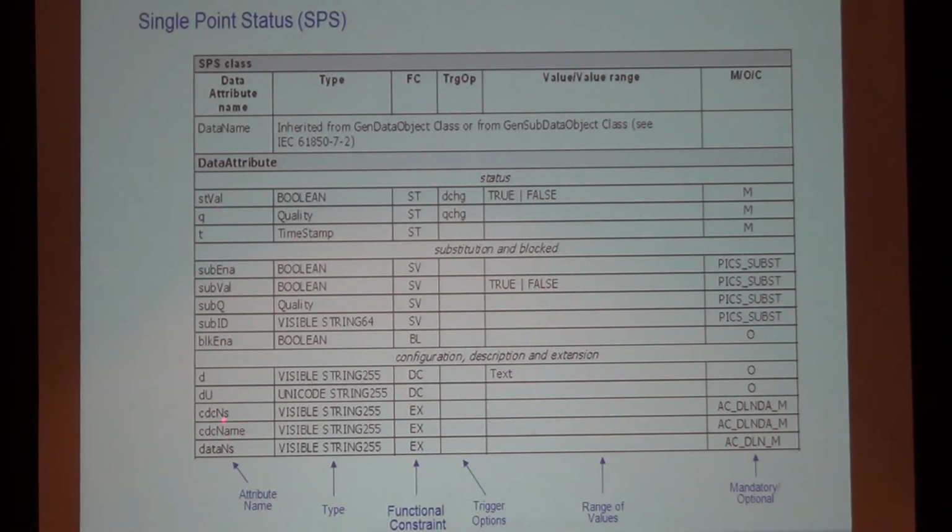And we also have these very interesting attributes that tell us about the namespace of the object. They are optional, but these are important attributes, because if the supplier or the developer of that object has provided some proprietary extensions to it, these objects here tell you that, in fact, there's a proprietary extension of this object. So it gives you the information you need to be able to understand the context of the object. All that information is available to a client by querying the device.